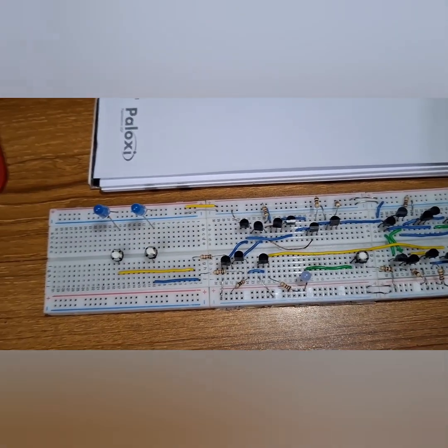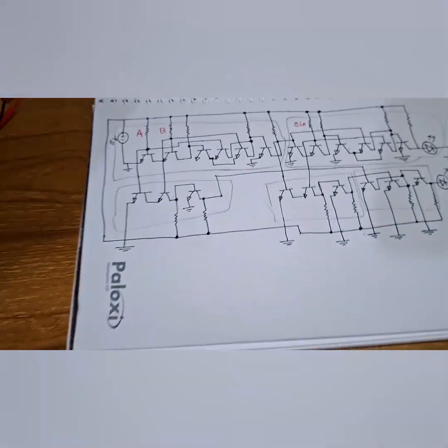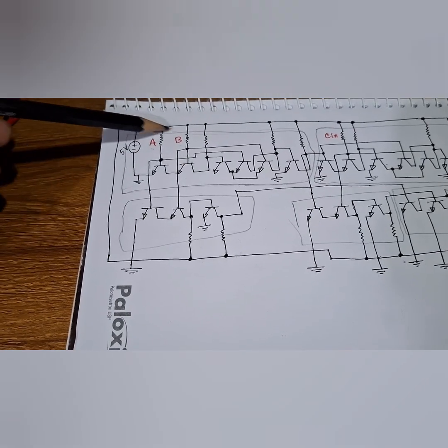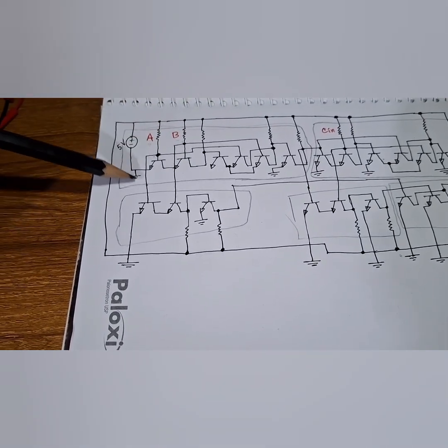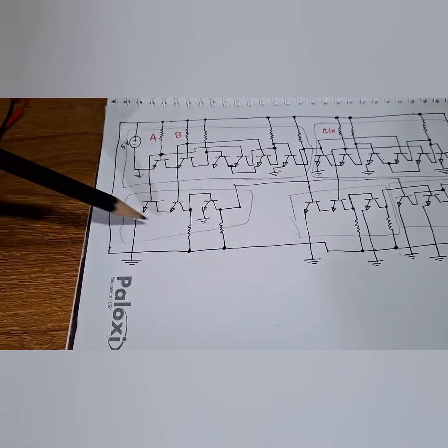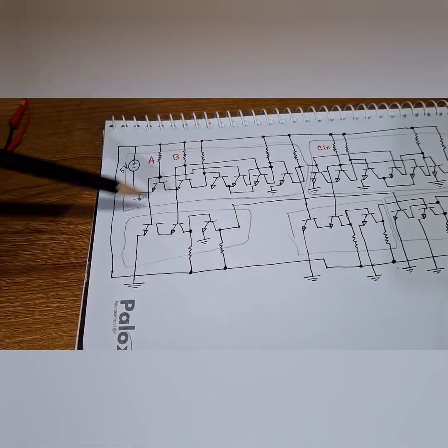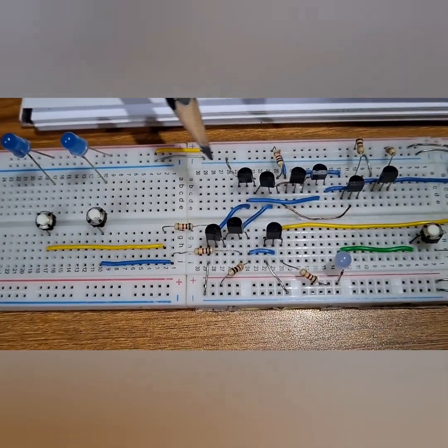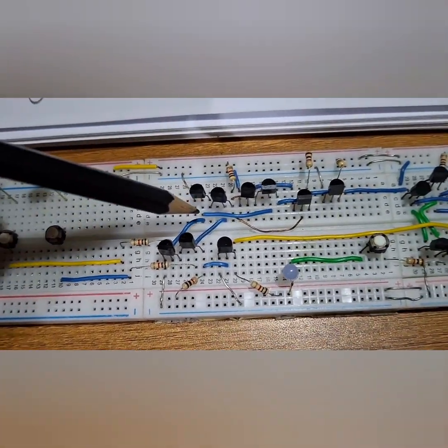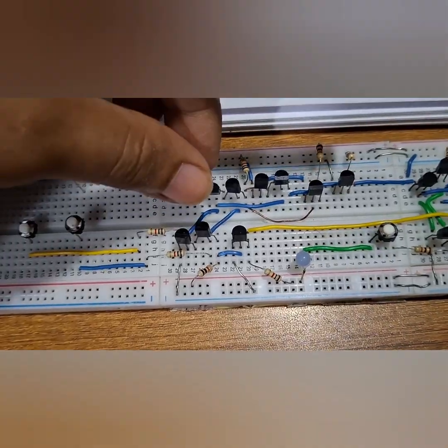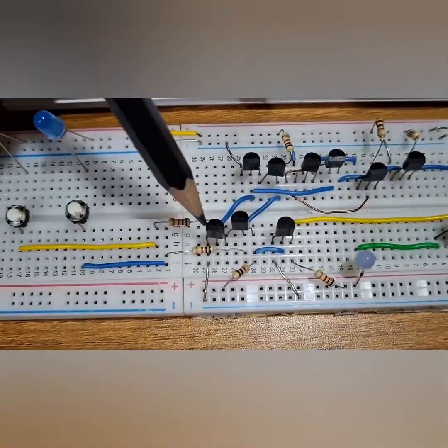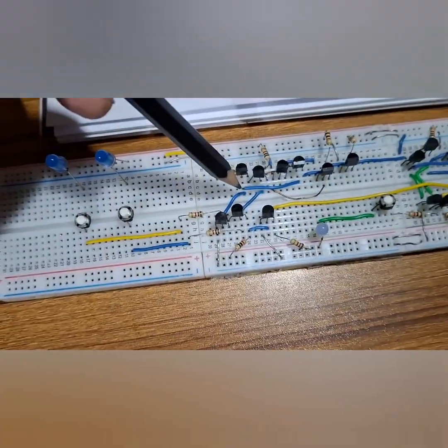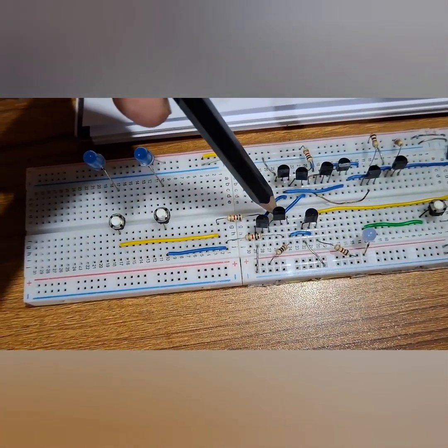To see the input, we will look at the diagram first. In the circuit diagram we see we have given inputs A and B to the first 2 transistors of the first XOR gate. That also connects to the first 2 transistors of the AND gate. So we can take the connection from here or here, and both are a common point. We look at these first 2 transistors of the first XOR gate. The first transistor's base comes into the base of the first transistor of the first AND gate, and the second transistor's base comes to the second transistor's base of the AND gate.